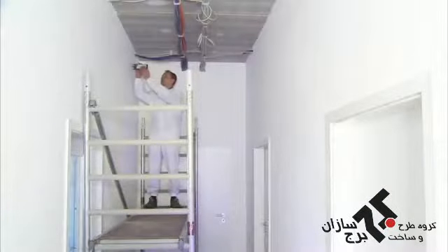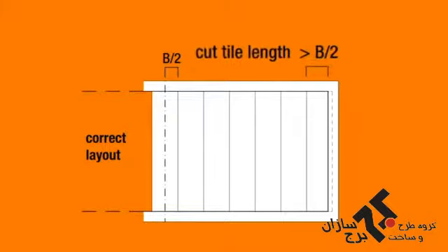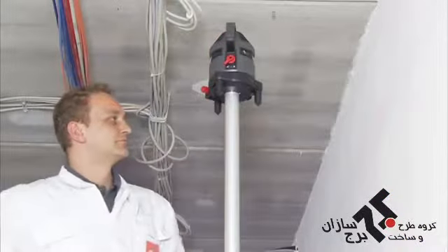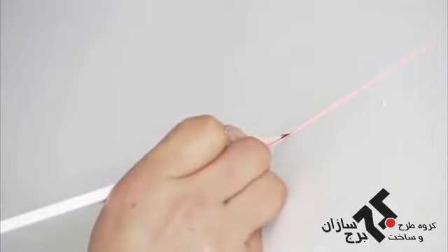After the room, with a maximum width of 2.5 meters, has been measured, the reflected ceiling plan, thus the visual layout of the ceiling, must be decided. Starting from the middle of the corridor, the layout continues in element widths, here named B. Please ensure that none of the cut tiles are smaller than half the tile width, as the resulting appearance is aesthetically unpleasing. Now we move on to the installation, where of course cleanliness also needs to be regarded.